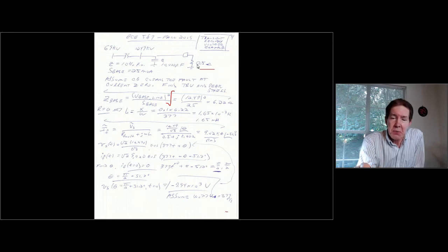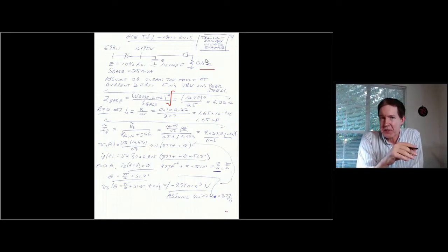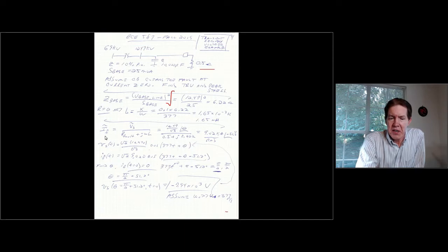If I put a little bit of fault resistance in here, now I'm changing that relationship. So when I hit a current 0, that source voltage is no longer at a peak value. So I need to do this calculation to figure out what the source voltage is when I hit the current 0. So I'm calculating the steady state fault current.